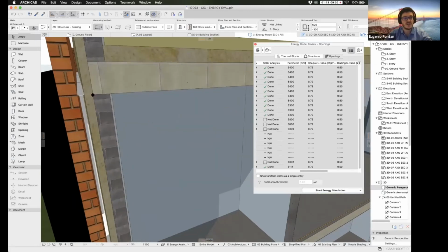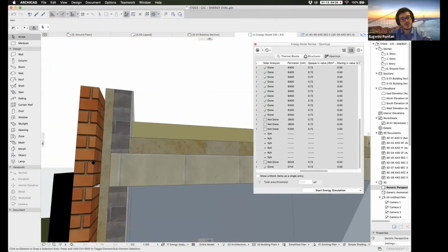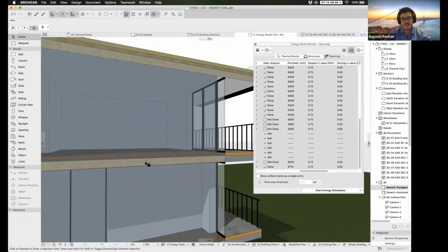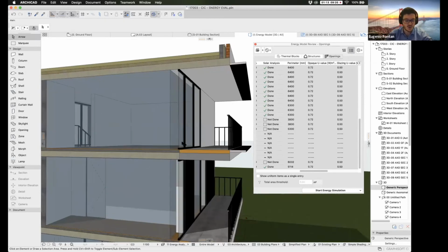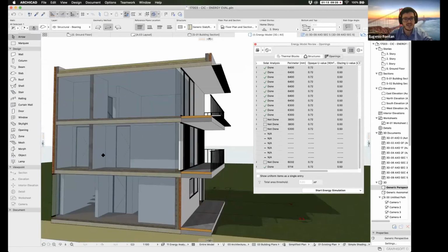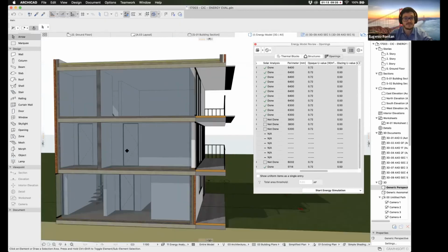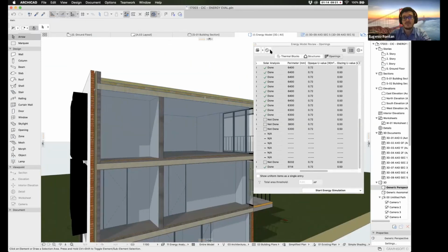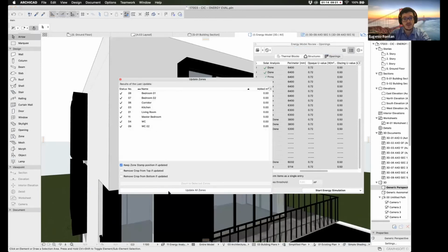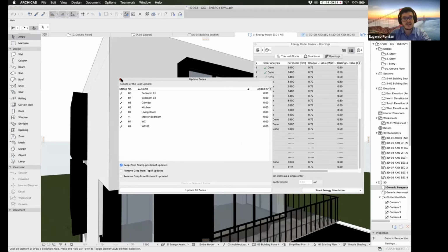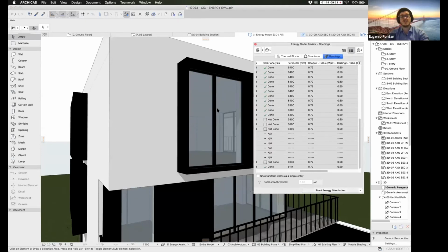Of course, we haven't finished the top of the parapet, but this ventilation chamber is just to ventilate the space. It's very rough, and you can see that these elements are not totally defined. The more we define, go into detail and tweak the construction details by playing with the building materials, the more accurate this analysis will be. But I wanted to show that if we improve certain elements and I now update the zones and update the energy model review, and we do a last energy simulation, we will see the results.